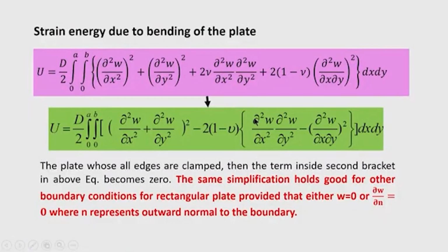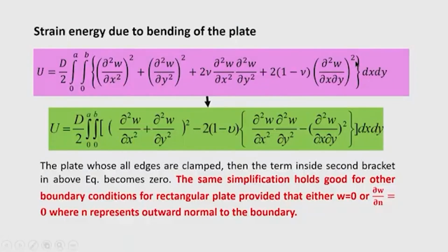Now, you can use either of these expressions. Even if, say, the shape function is not very clearly defined, because in the simply supported case it is clearly defined by Navier and it satisfies the boundary condition exactly. Now, in some cases when the shape function is not defined properly or not tested properly, then we can use the original expression also. There is no harm in using the original expression. The original expression is the general expression, and here you can see del square w del x square, whole square. That means if you assume a deflected surface, then this curvature square you have to integrate.